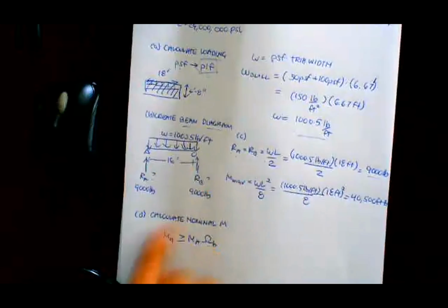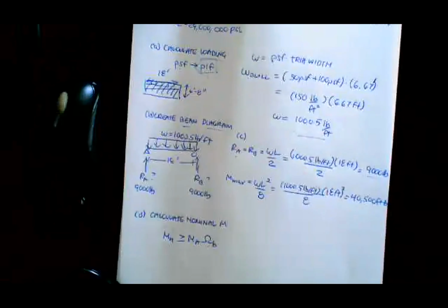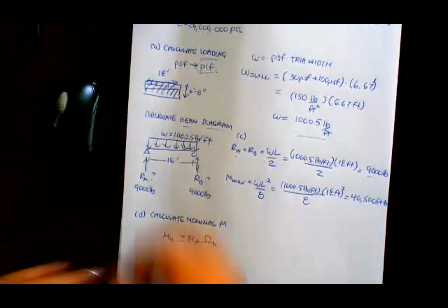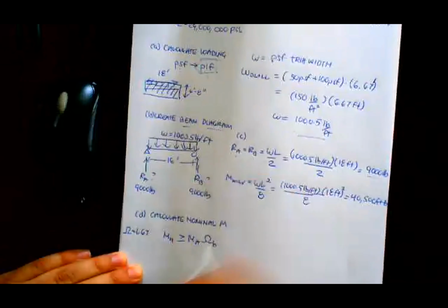Because this nominal moment should not be less than the safety factor times the load condition that is possible on this building, because that would be terrible. We always put safety factors because you never know when people are going to exceed the expected values. So we boost it up for the worst case scenario with a safety factor. Specifically, the ASD method tells us that the safety factor should equal 1.67 for moment.